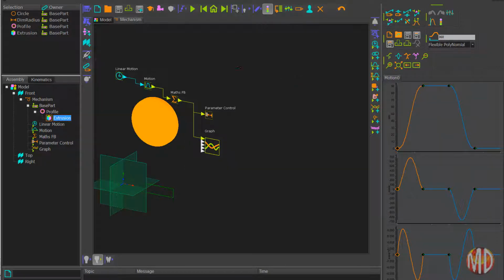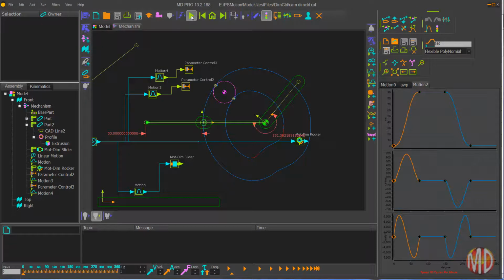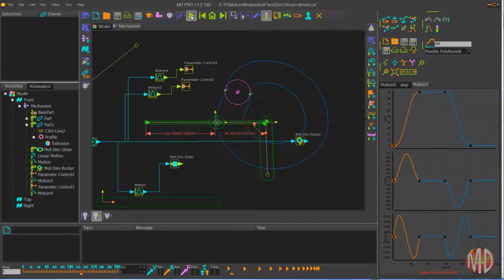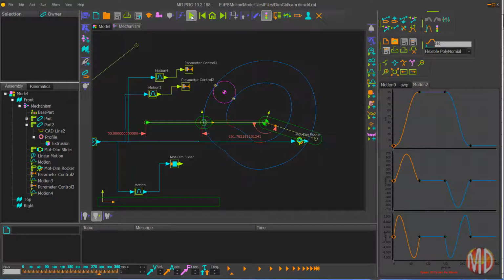You might be wondering why you would want to control dimensions dynamically. The main reason is to help with cam profiles. If a cam has a dwell, you might want to lock the cam follower mechanism to prevent residual vibrations. By increasing the diameter of the roller, you can prevent the locking mechanism over-constraining the follower, as this will have the effect of relieving the profile during the dwell.